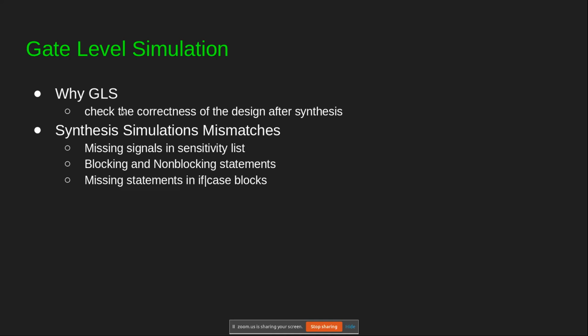So gate-level simulation is simulation on the synthesized netlist. Basically the flow is similar, like if you are using iVerilog, it is similar. The good thing about this is after synthesis, in the synthesized netlist, the inputs and outputs are the same, so you can use the same test bench.